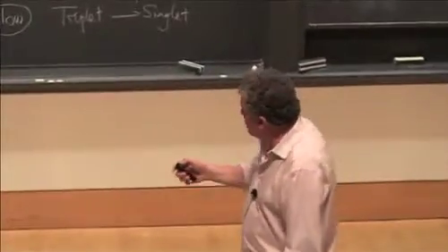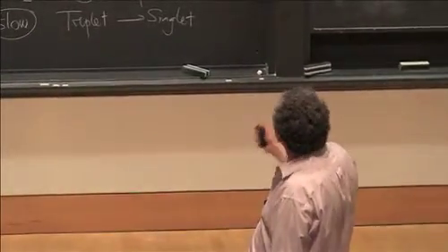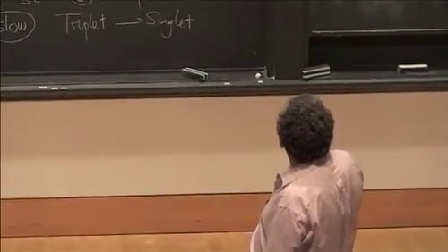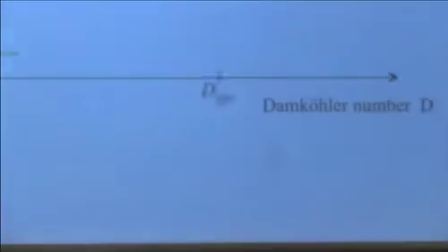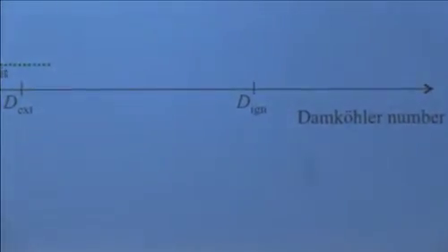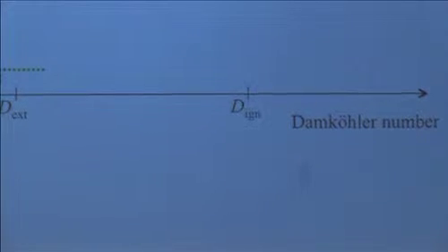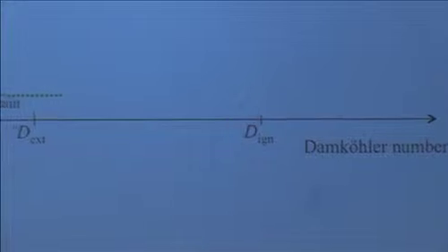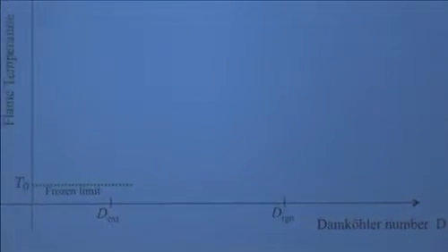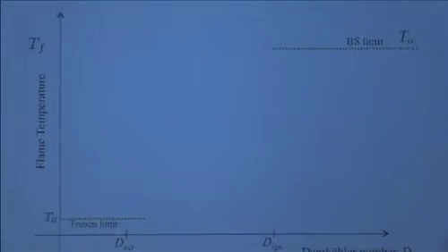Okay, so this is the frozen limit, and the mass fractions of the fuel and oxygen just diffuse into each other, just pure mixing. So this is the limit of pure mixing. This limit is the limit of Burke-Schumann when D is very large, where all the fuel and all the oxidizer is consumed at a reaction sheet. And what I'm interested to plot here is the maximum temperature in the field, which, in the Burke-Schumann case, is clearly the flame temperature.